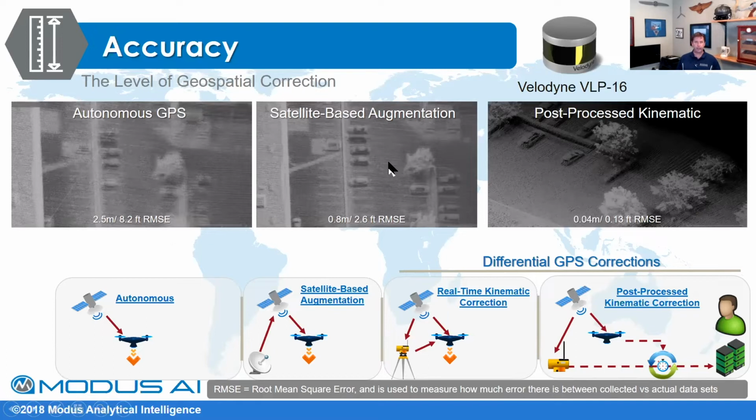And so it's getting its GPS coordinates, and hopefully it's better than your drone's. It better be. And then your drone is receiving it, and the processing unit on the drone is making those corrections and comparing those two in real time. So there we're seeing, usually I'm in centimeters, about 8, maybe 7 centimeters of absolute accuracy in real time if you're using that scheme.